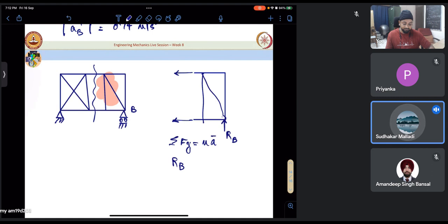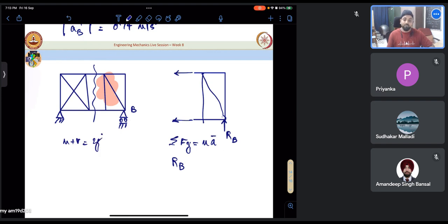Yeah, that is what instability is all about. Yes, it's not stable. That was the question. See here, m plus r would be equal to 2j, but it is still not stable. Why? Because this is not being balanced. So we need to analyze it thoroughly, to see if the members are arranged properly in order to conclude something on stability. Is it clear? Okay. Thank you.